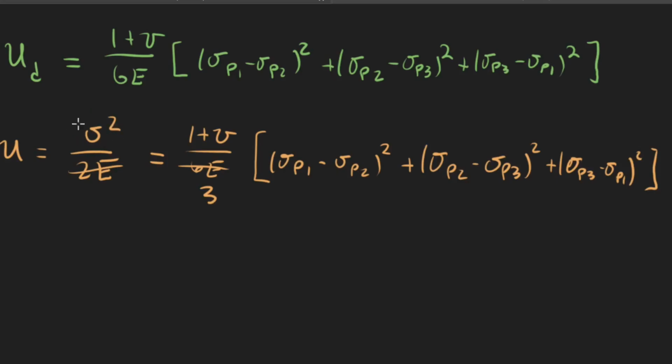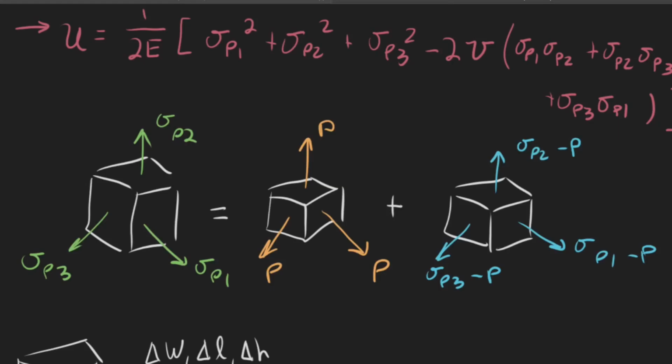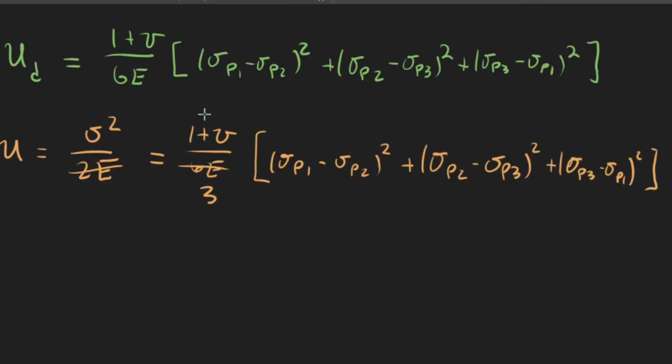Now to get our equivalent stress in terms of just this state of stress, the last thing we have to worry about is Poisson's ratio. And it turns out the Poisson's ratio, based on an assumption we made earlier, is equal to 0.5. Because we assume there's no volume change for this distortion component, nu right here becomes 0.5.